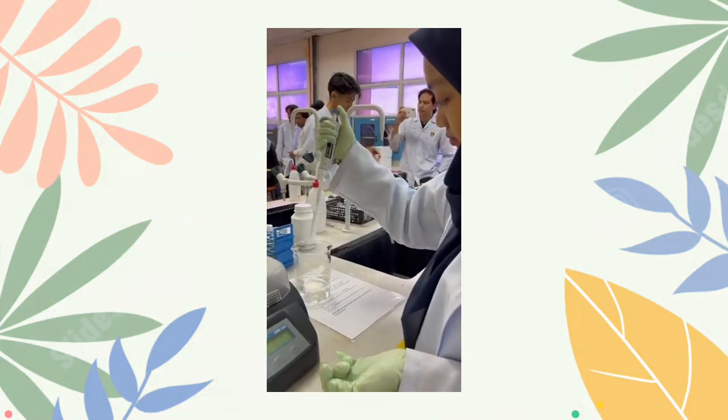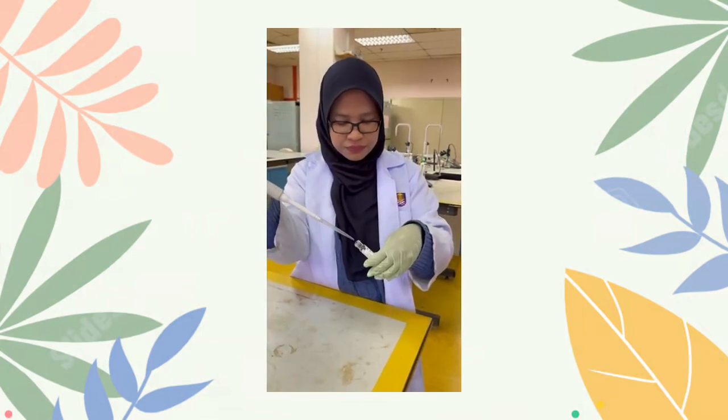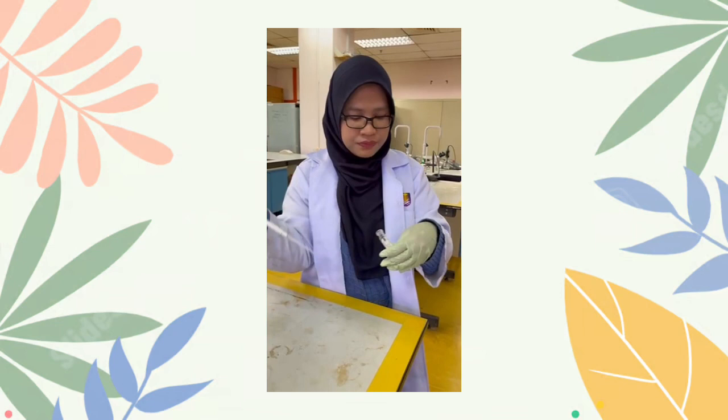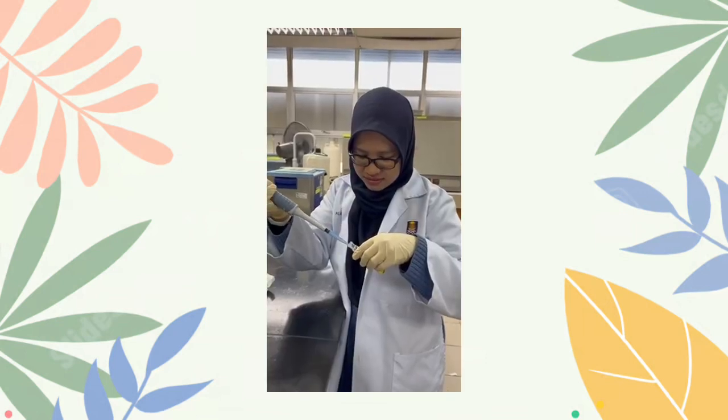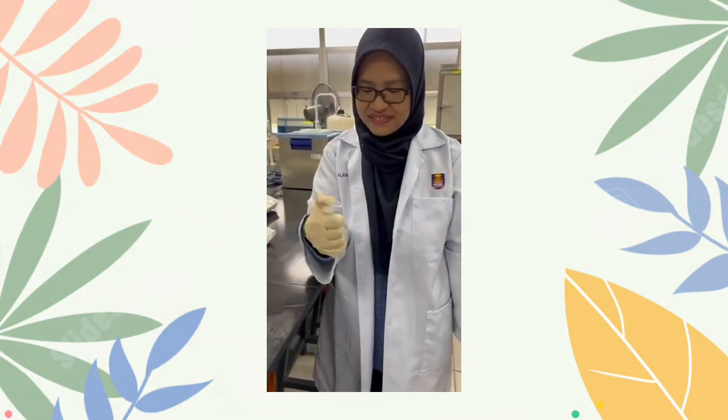Prepare 2 vials for sample. Mark the vial for sample. Suction 2 ml of water sample using a pipette. Hold one vial at a 45 degree angle. Use a clean volumetric pipette to add 2 ml of sample to the vial. Close the protective lid tightly. Repeat for the other sample. Invert gently several times to mix.